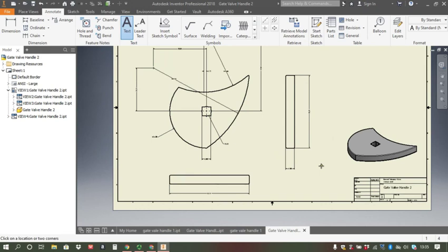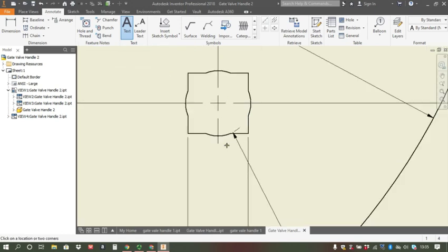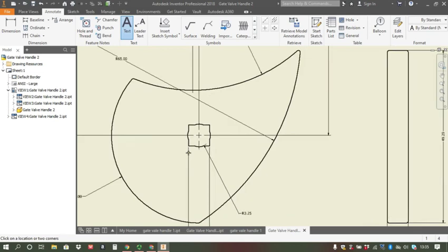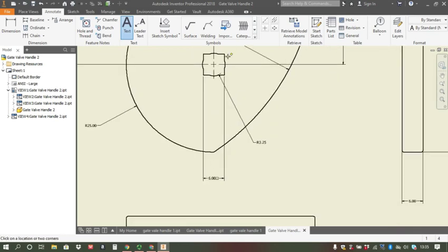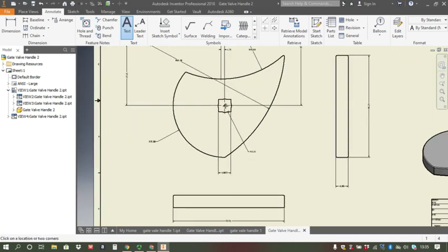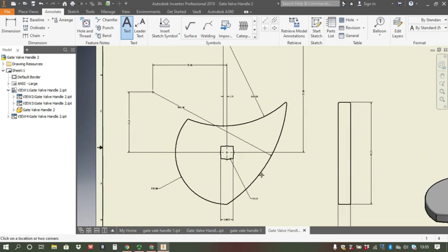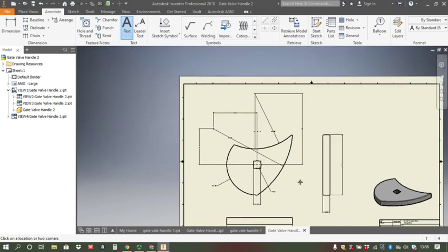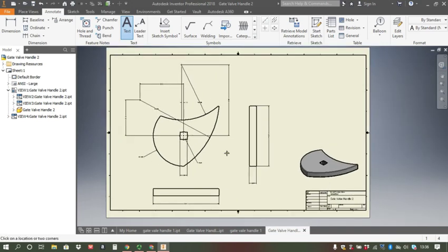and the more items and the more curves and the more parts you put onto it, the more complicated it gets, the more dimensions will be there, and the more things you have to remember. But you should remember quite simply that if everything is referenced to this center, then we only need a dimension for this one. We need to tell it that it's 6 millimeter box or 6 millimeter square for the square in it. You need to then reference everything else to that center, and anything else that is from that center that is not already referenced, as this one is going to need a height and a width, and a height and a width. They're also, when they're curves, going to need a diameter. So make sure and check that everything that you need is there.